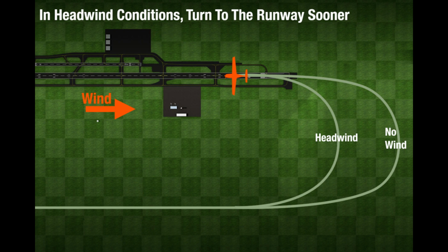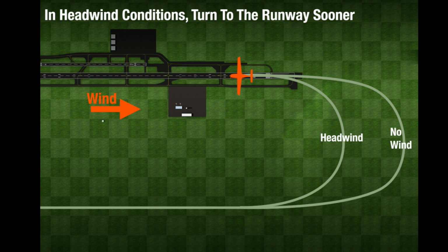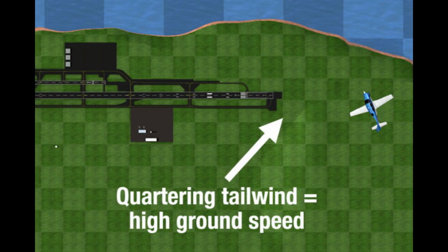The basic procedure in these approaches involves closing the throttle at a given altitude and gliding to a key position. Starting with the same energy, airspeed and height each time the throttle is closed makes the maneuver more predictable. The key position, like the pattern itself, is not the primary objective; it is merely a convenient point in the air from which the pilot can judge what to do such that the landing occurs at or just beyond the desired point. The selected key position should be one that is appropriate for the available altitude and the wind condition.